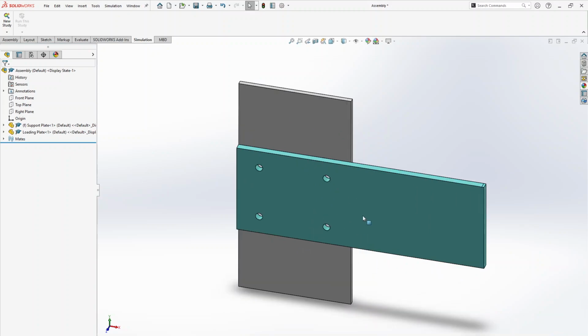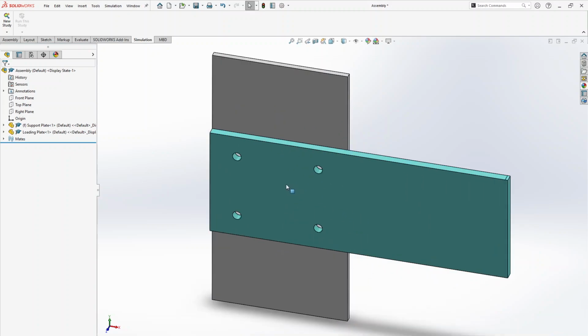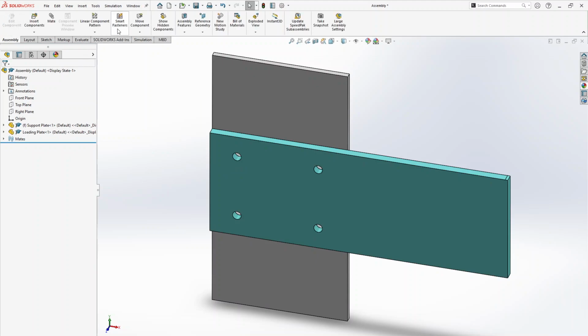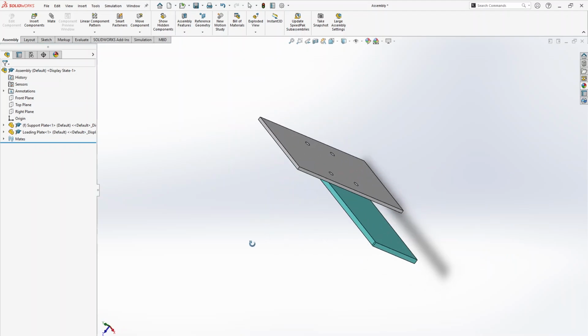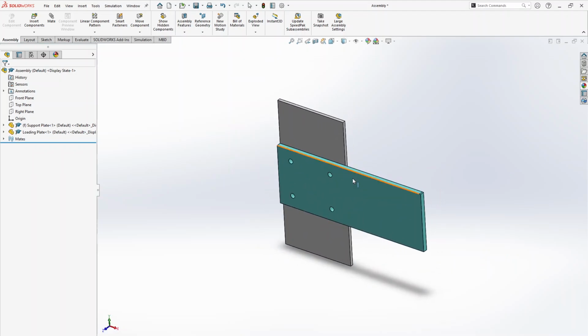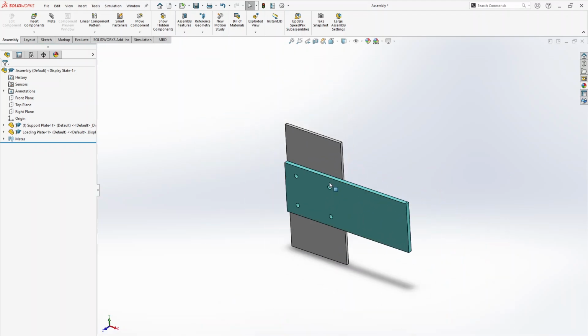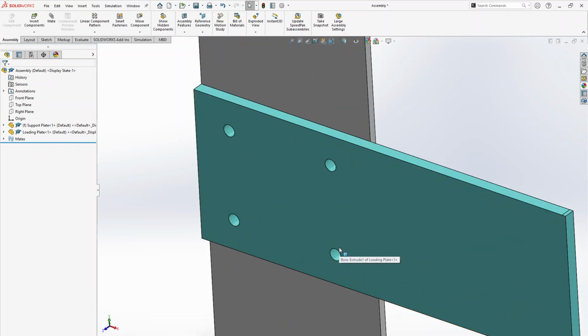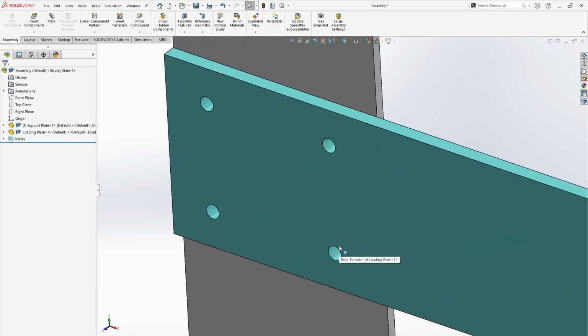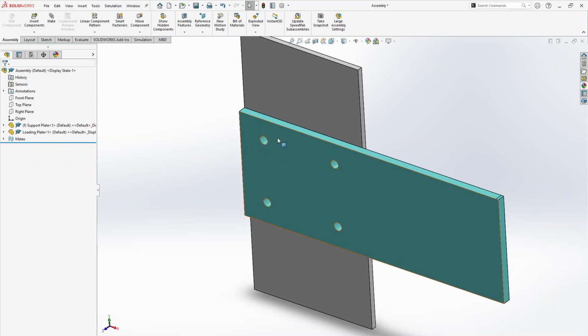As you may guess, we don't really need to model and define the fastener or smart fasteners here. SolidWorks can do the legwork and do the simulation more precisely and accurately, and it's highly suggested that we go with the way that SolidWorks defines the connector rather than actually modeling and putting the bolts here. And that's what we are going to do.